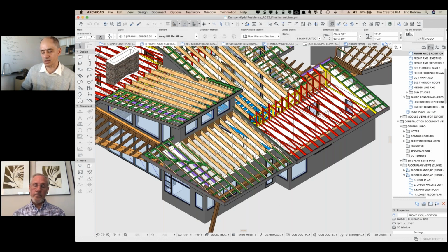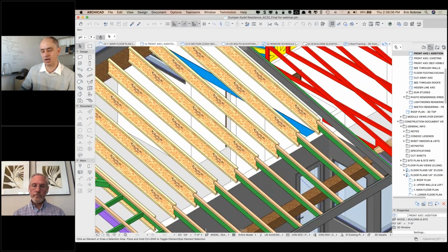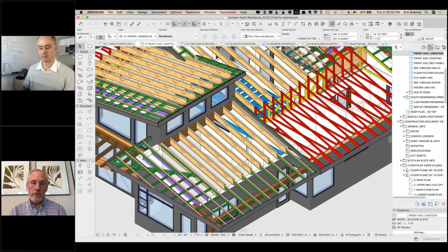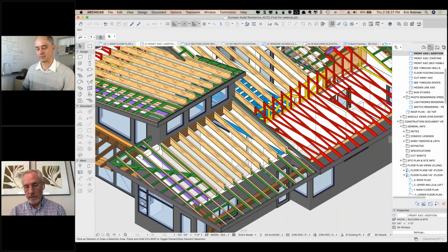Right. And I'm noticing this detail here, which you had explained, is that the TJIs are not able to go outside the building, so you have to switch the support to things that are weather resistant. That's right. Those were 2x6s, I think, with strapping on top to tie into the top of the TJIs. And I wanted a thinner profile too than just a big thick 14-inch TJI. I think they were 14-inch or 11 7/8 anyway. I wanted a thinner profile for the overhang for the fascia. And we had sloped soffits on all of these.